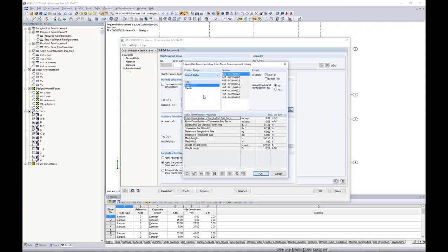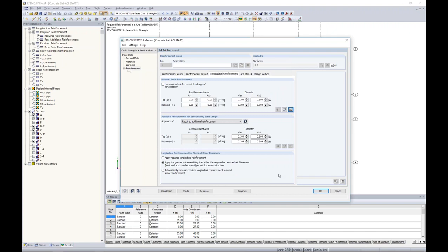Now, if you jump down to the United States, we have welded wire fabric reinforcement already selected here, or already an option to select within the program. I know when I did design for precast concrete bridges, we only used welded wire reinforcement. So this is nice that you don't have to manually apply these specific properties of our reinforcement, but you can bring them up from this library directly here.